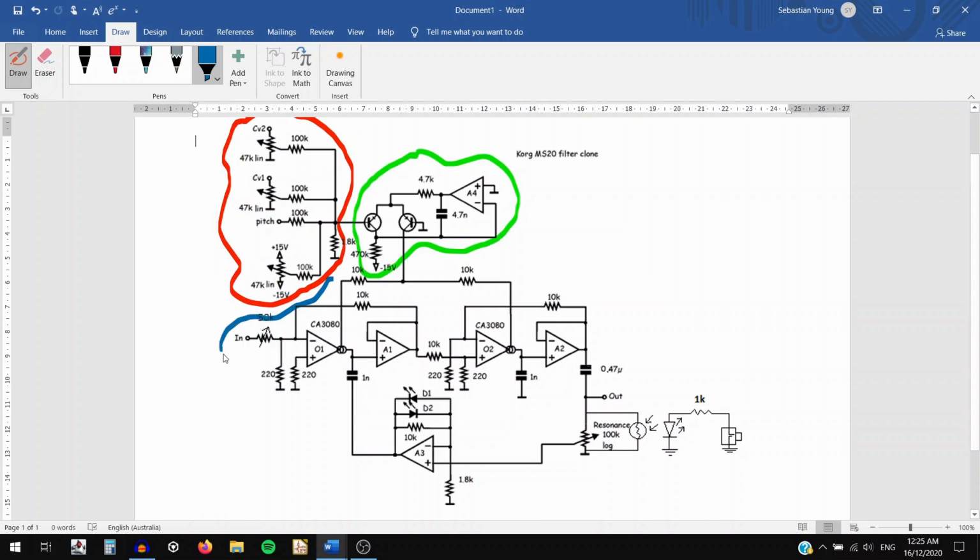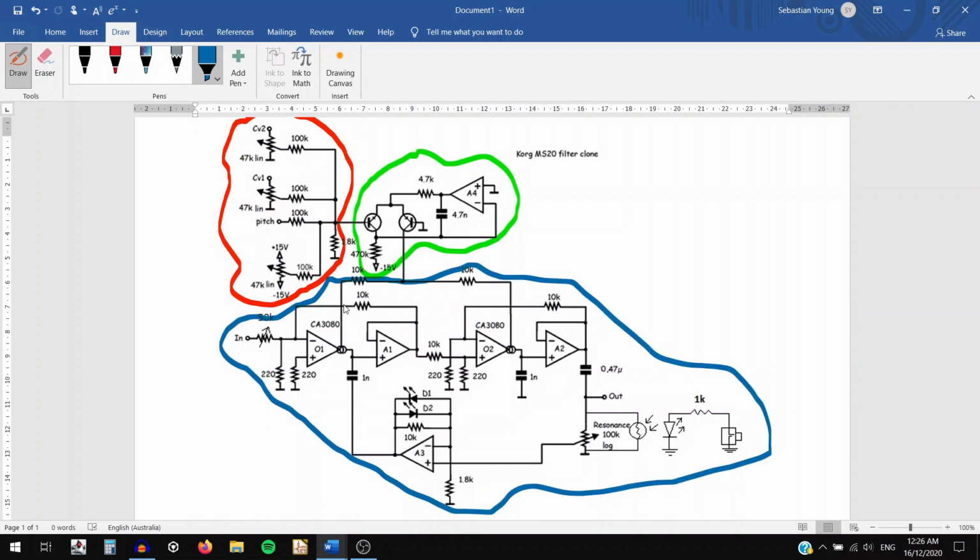So next we come to the actual filter itself, which is two identical Sallen-Key type filters. You can see that we have a few op amps floating about, but what exactly are these funny looking ones here with these Venn diagram looking things on the output? Well, these are known as operational transconductance amplifiers, or OTAs for short, which essentially work as a voltage-controlled current source. They are actually found at the heart of heaps of analog synth circuits just because of how useful they are. In our case, these CA3080s have been replaced with LM13700s, but they basically work the same as each other.